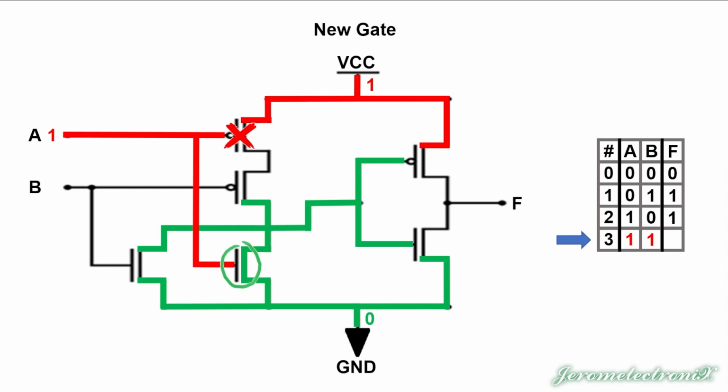They stop over there at the 2 gates at the right, and we haven't done anything with B. Well, on the right, you can see that a 0 blocks the flow in the NMOS, and it allows the flow through the PMOS. It's allowing flow to a high voltage, so high voltage gets out. That's a 1. We could put that one on our truth table, but let's finish off B.